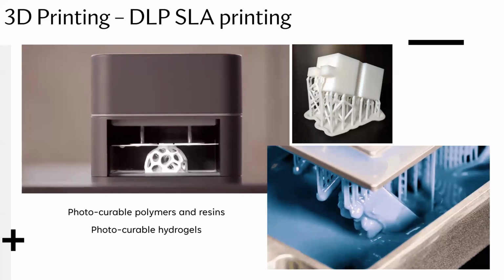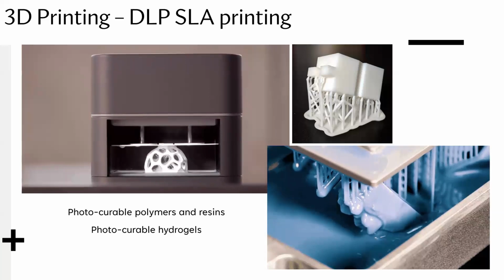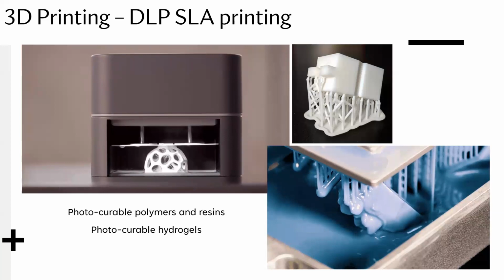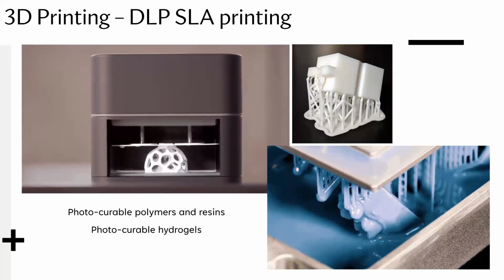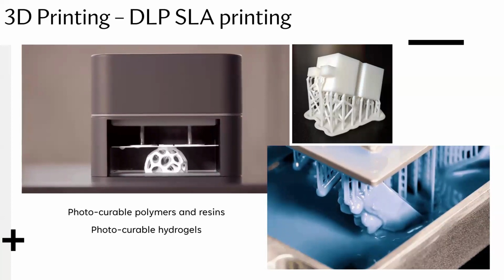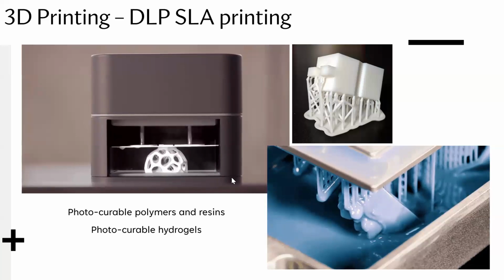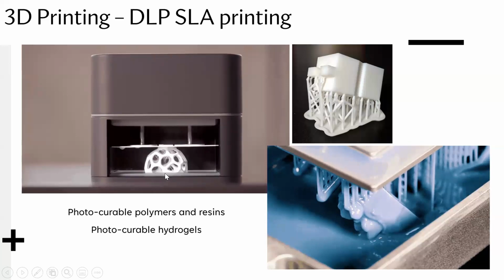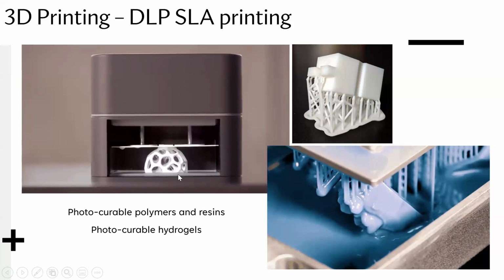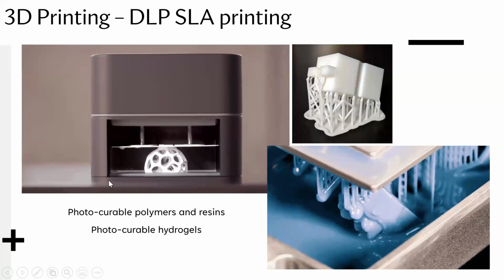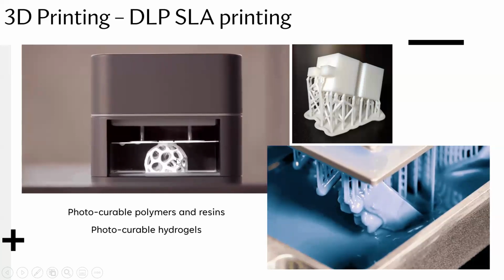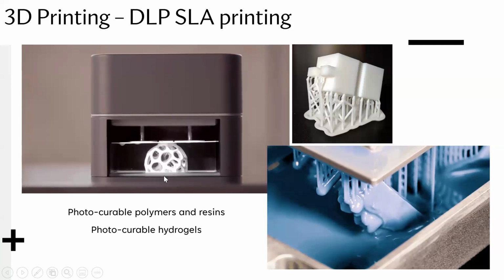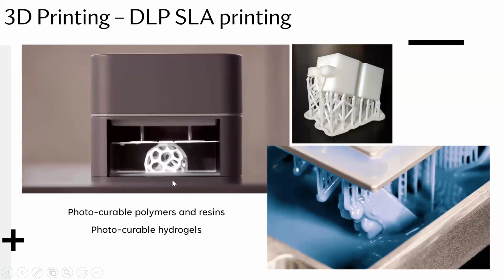Now, this cannot be done in all cases for all materials, and finding a suitable glass window is always a problem. So although you may not have thought of this as a big challenge, it is actually a very big challenge. The challenge again is that as you cure the material in this layer, that material then sticks to this glass window, and this glass window underneath is where light travels through and hits the object and cures the material.